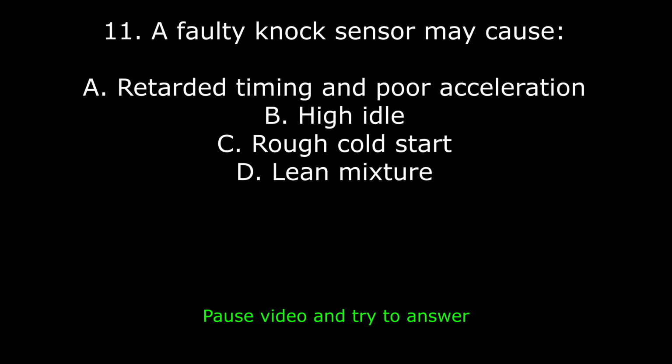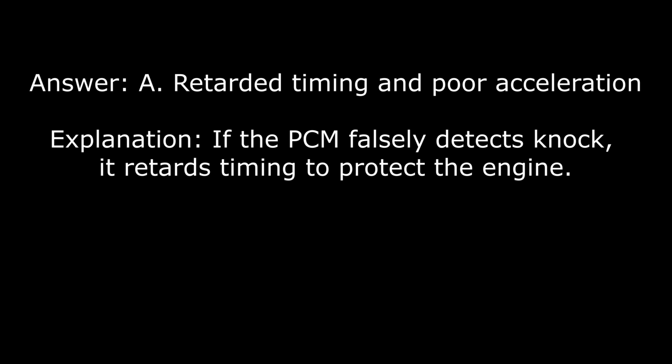11. A faulty knock sensor may cause A. Retarded timing and poor acceleration, B. High idle, C. Rough cold start, D. Lean mixture. Answer: A. Retarded timing and poor acceleration. Explanation: the PCM falsely detects knock and retards timing to protect the engine.